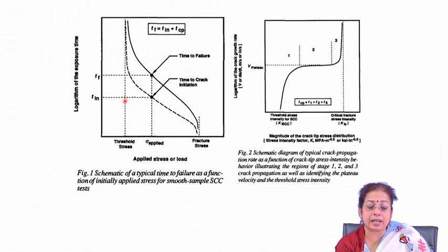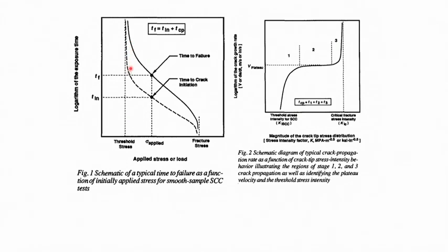On the other hand, as you increase the stress above the threshold stress, you will find that there is a time of crack initiation and a time of crack failure. Actually, at a particular stress there is crack initiation, and at a stress much higher than that of crack initiation, there is crack propagation. This time range between crack initiation and crack propagation decreases as you go on increasing the applied stress on the surface.